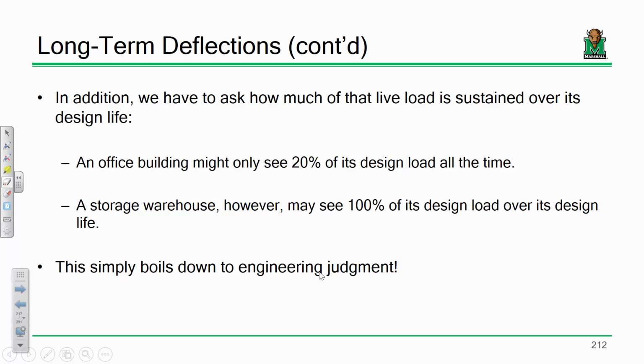Yes, sir? How does that change for bridges, where you don't have a sustained load? That's a great question. So the question was, how does this change for bridges? And the answer is the bridge code offers far more prescriptive means for assessing live load deflection. It specifically defines what load case you are to check when assessing live load deflection, and it specifically spells out your limits. So fortunately for bridges, deflection isn't really something that you have to guess at. As a bridge engineer you don't have to guess what load you are going to consider. The code specifically spells that out.